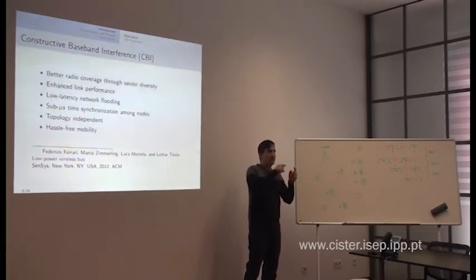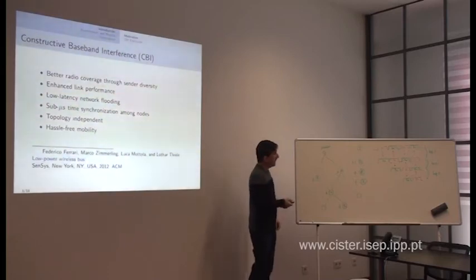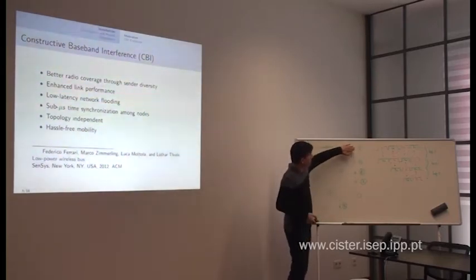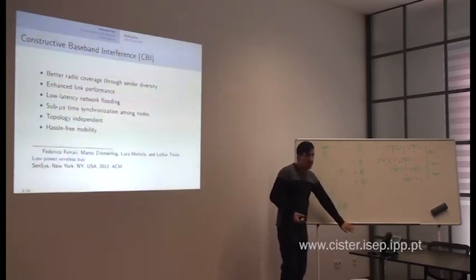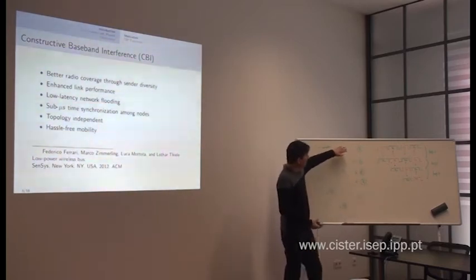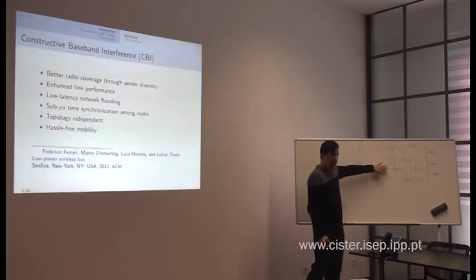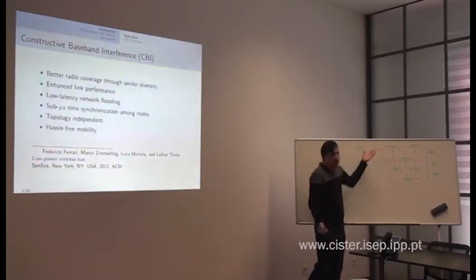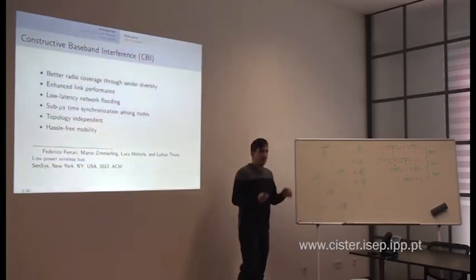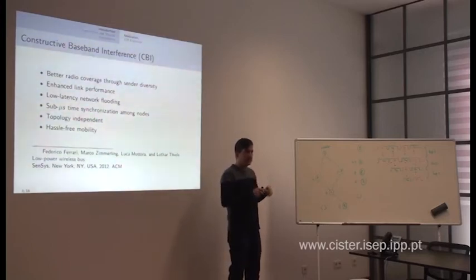Because they will know the time at which they have to wake up. This is just when you send the first packet. But you would expect the radios to be ready to repeat this cycle when you transmit again in the future. And therefore, it implies that when you transmit, they are already ready to listen. Because if this node, for example, were turned off, when you transmit, nothing will happen, right? So they will have to be time synchronized.